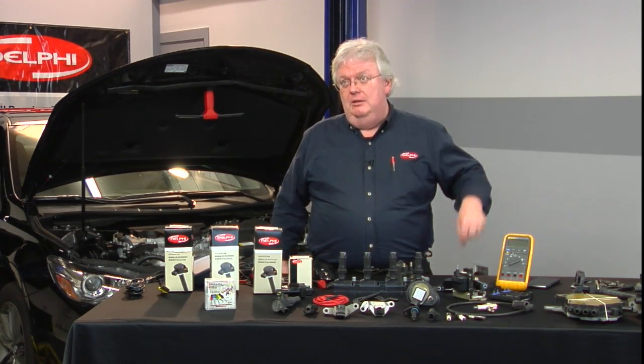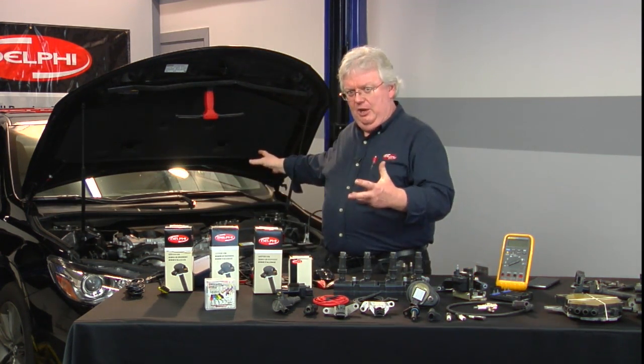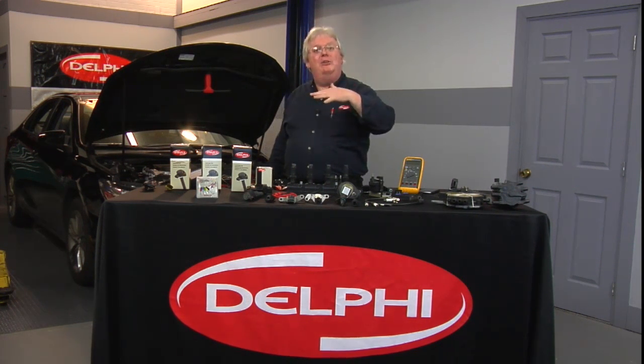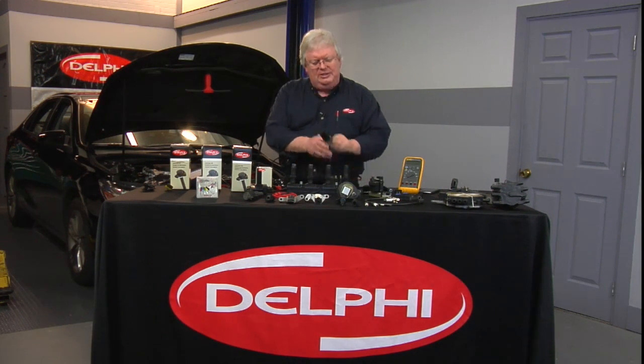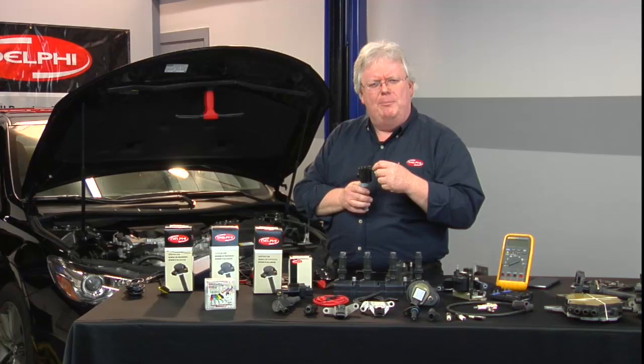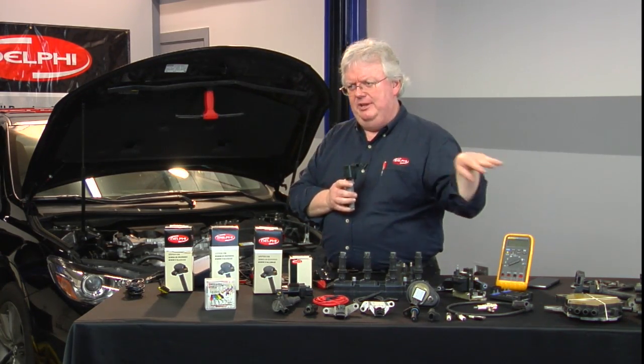And if it was on the Ford Flex, the red vehicle, that was used for just B+, to see if I had a good power supply, see if I was getting a voltage drop, basically, to the power source, to the simple 2-wire Ford Coil-On-Plug. So the purple wire is the one I amp clamped, and I think that was a green trace, the amp.